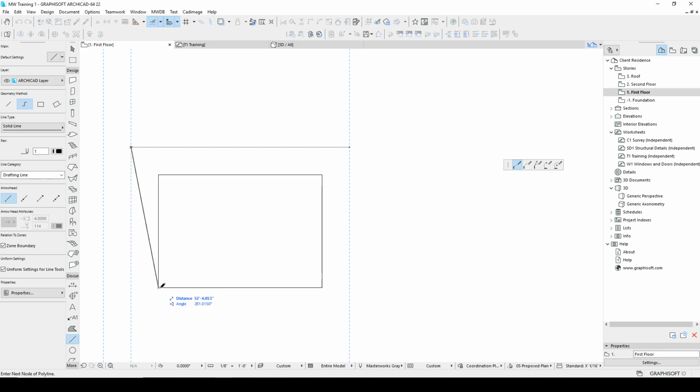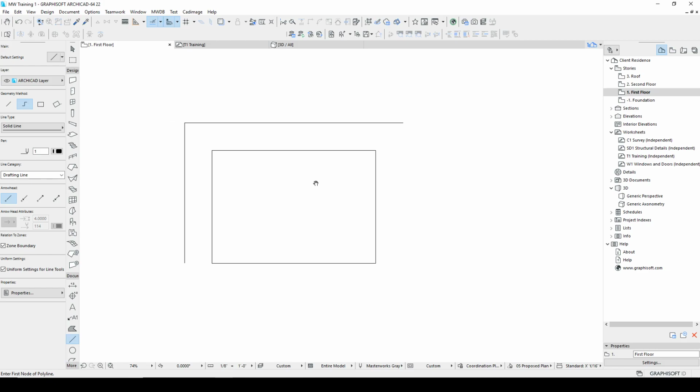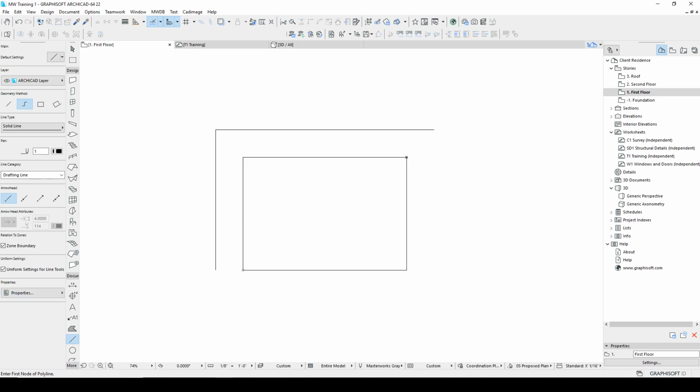Let me move my origin again. And now I'll go X minus 10, Y0, and I'll stop there by hitting enter again. So I'm able to place geometry relative to a user coordinate that I get to move around by hitting Shift Alt. Fantastic little feature there. Get to use it and you'll love it. See you in the next video.